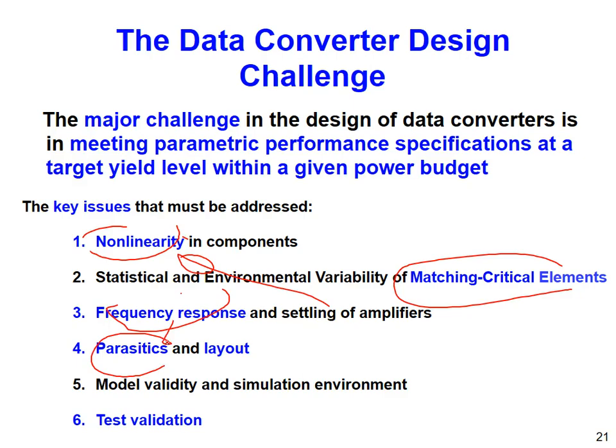For my student, from presim to postsim, more than 3 bits were lost. That is due to parasitics. So we need to figure out every kind of detail. Because you have a lot of parasitics, you need to know which one or which ones cause the most damage, then try to get rid of that, to reduce the parasitic. It's hard work.